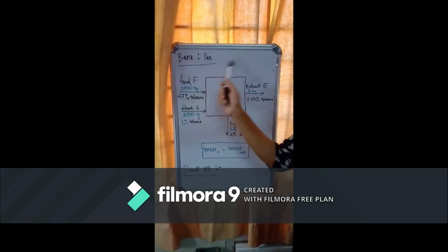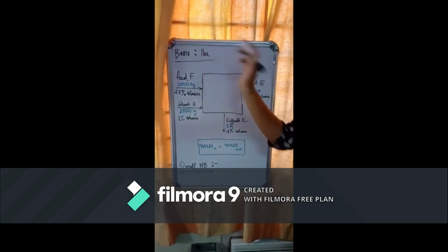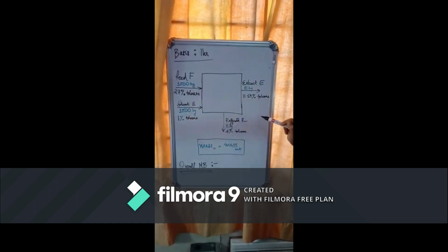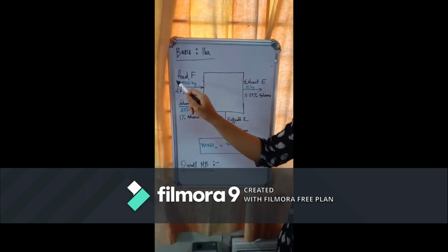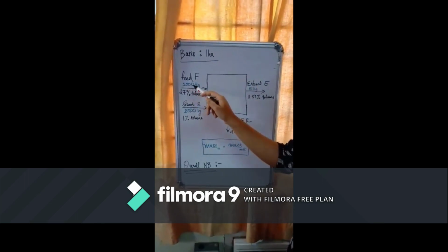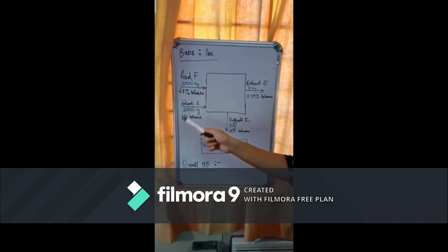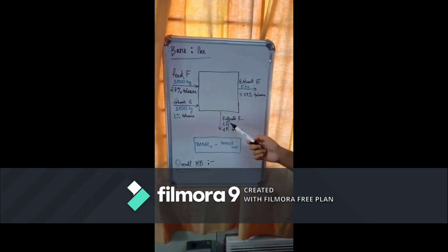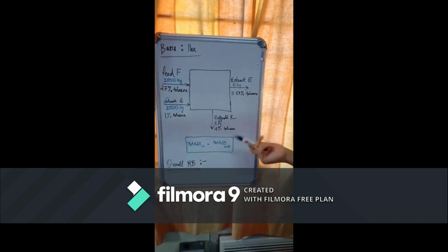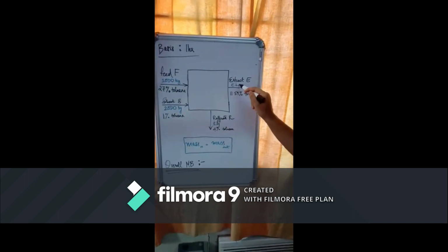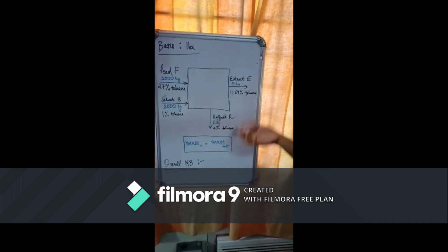Noting down the basis for the whole problem. The basis, because the mass flow rate is per hour, is 1 hour. Then you draw this system diagram, which I've done. You have the feed, which is 1000 kg per hour. So 1000 kg, because the basis is already written, and 27% of it is toluene. Solvent 2000 kg, 1% is toluene. Raffinate, we don't know what is the mass flow rate. So basically we write R kg and E kg for raffinate and extract, and 4% and 11.59% respectively.